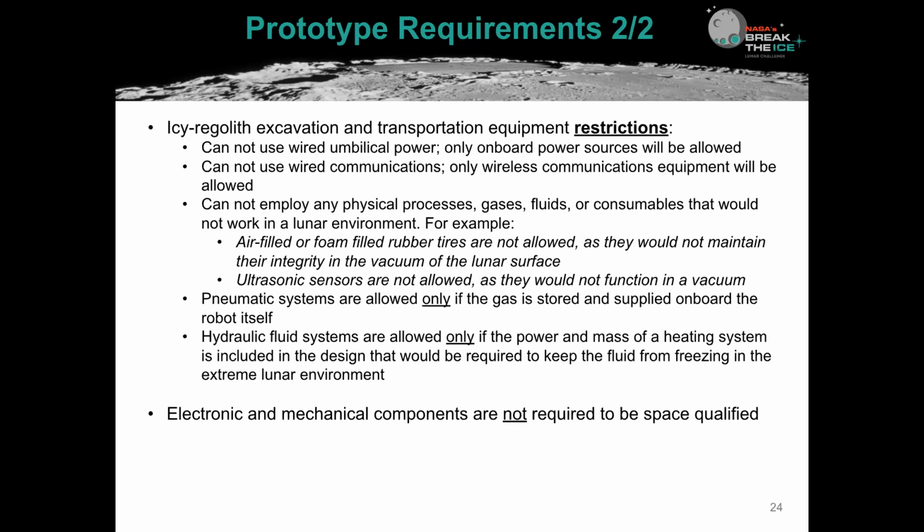Cannot employ any physical processes, gases, fluids, or other consumables that would not work in a lunar environment. Some key examples would include air-filled or foam-filled tires, as they would not maintain their integrity, as well as ultrasonic sensors, for example, as they would not function in a vacuum.